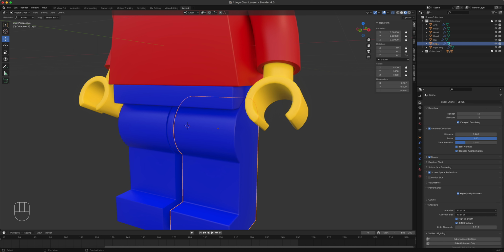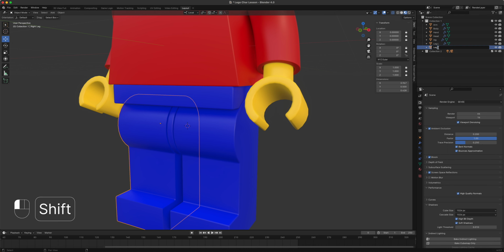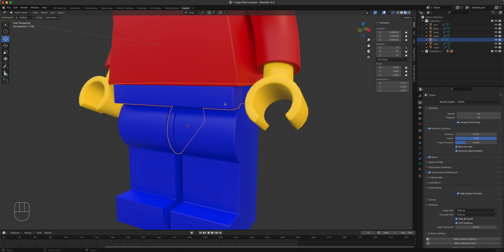So we're kind of training you in Blender armature naming convention so that you can symmetrize the bones later on without typing the name. It knows when you put .L or .R that it's for the other side. So this one is also leg.R.